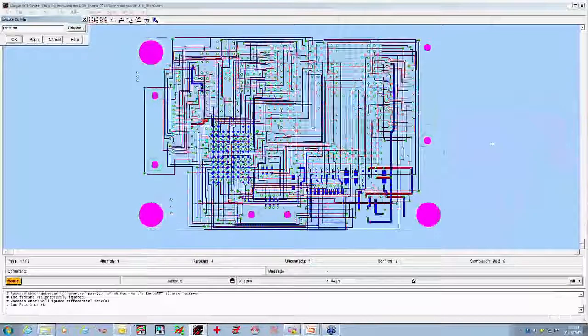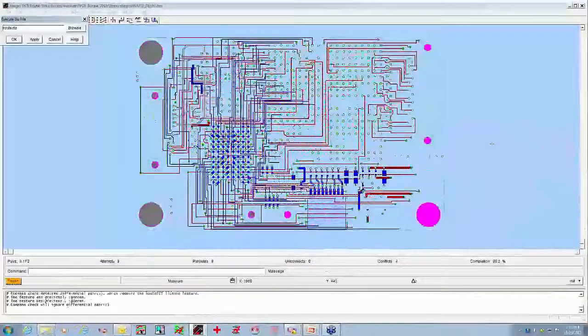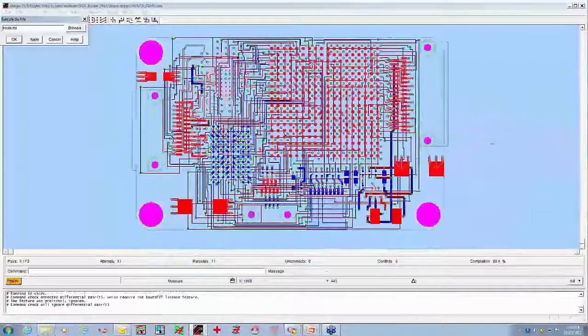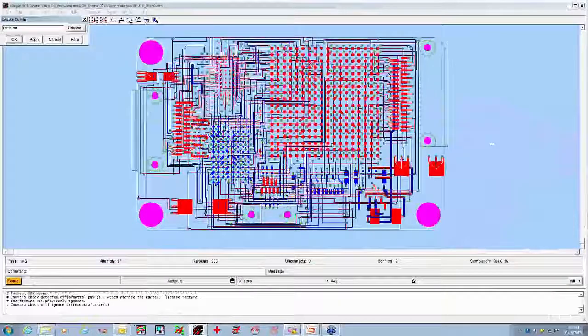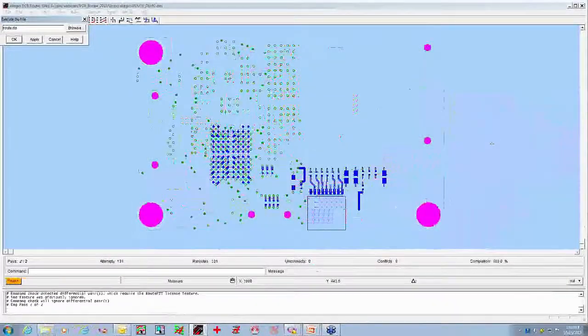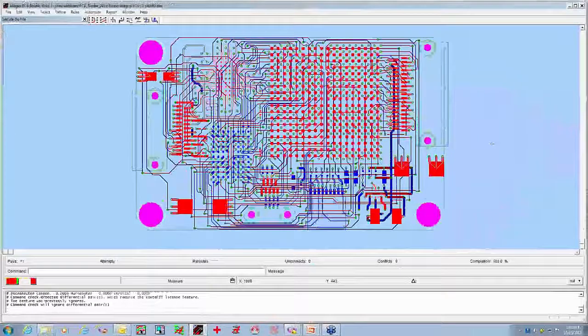It's going to do a clean right now. It did disconnect 1 wire. And now I'm hitting it with another route phase to remove those last conflicts. So now I'm at 100%. There's no conflicts left. I'm doing another optimization pass, and now I just did my miter as my last function.